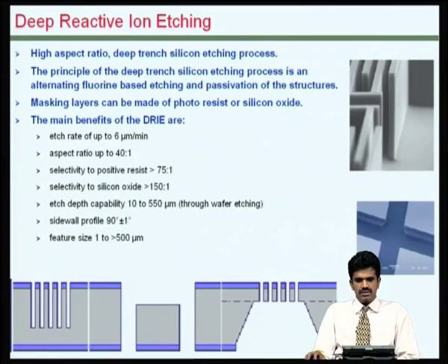In this case, what is usually done is that we remove material partially and then do a round of deposition, in which the side walls get coated with something like a non-stick surface, so that in a subsequent etching, when the atoms get displaced, they do not stick to the side walls, rather they come out of the cavities.